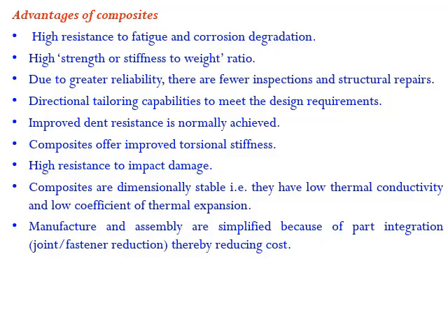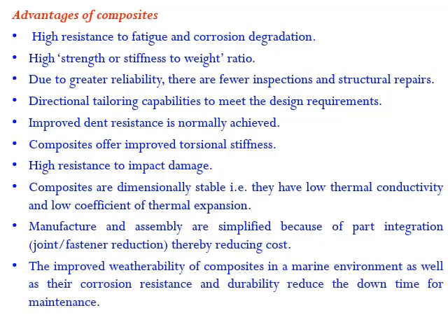Manufacturing and assembly are simplified because of part integration, thereby reducing cost. Whenever we go with the composite material, a single integrated part is manufactured rather than forming joints and all. There is improved weatherability of composite materials in a marine environment, as well as corrosion resistance, and durability reduces the downtime for maintenance.